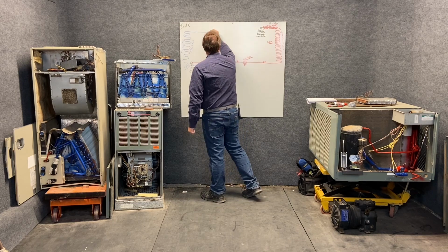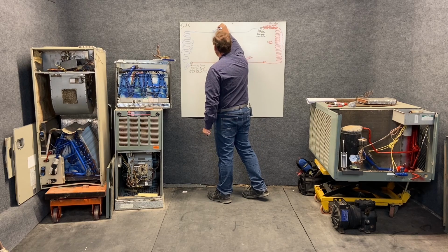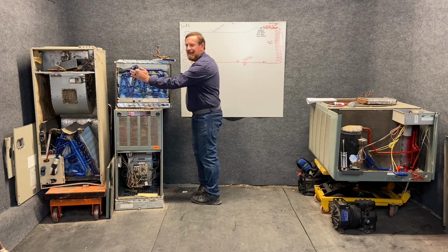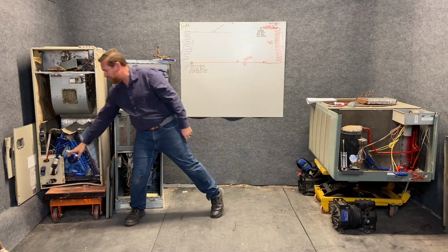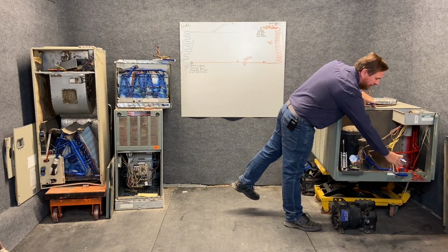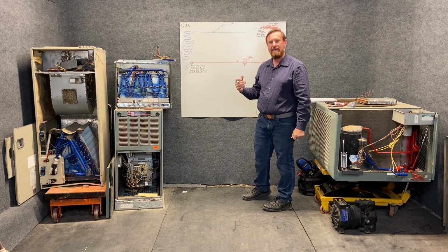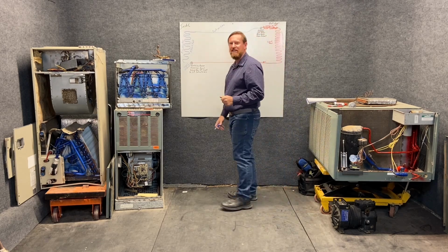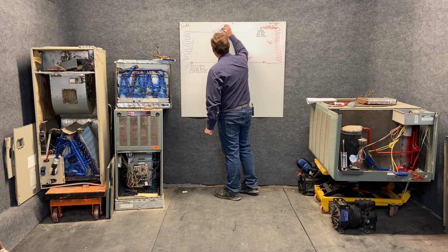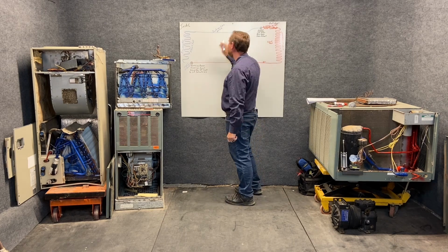So now that we leave our evaporator, we're going to have our suction line. That's going to be this big line, the thicker line. It usually has insulation on it, like this example. It's going to go all the way to the outdoor coil through a valve. It's going to end up all the way back to the compressor. So we have a complete cycle. But it's not just called a suction line. It's also called a gas line, suction line, or simply a suction gas line.